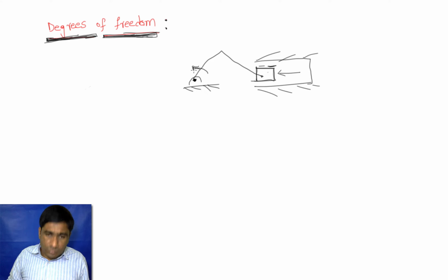And we need to know whether this particular mechanism has only 1 degree of freedom. We know it's only 1 degree of freedom because we have already seen this one. But how to know that before using it in the machine or in the engine? So we need to apply the degrees of freedom formula for this one, and if it is satisfying that the output motion has only 1 degree of freedom, then only we go for this type of mechanism. And that is about degrees of freedom.